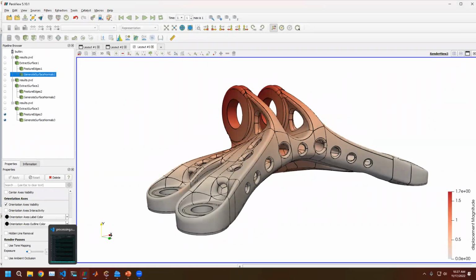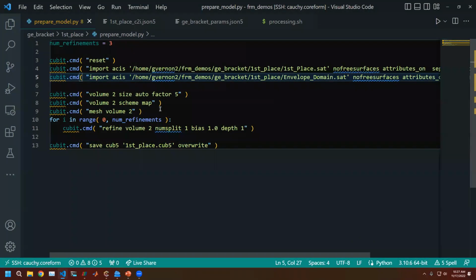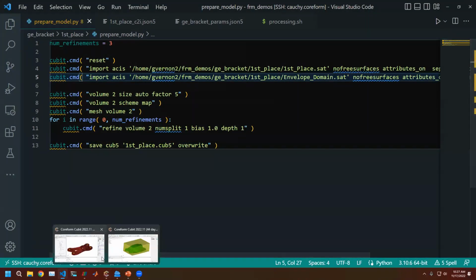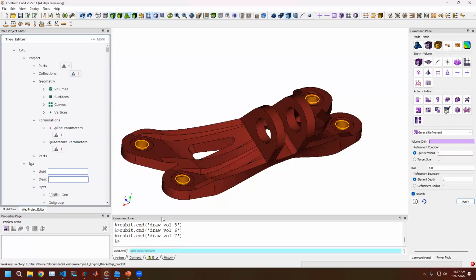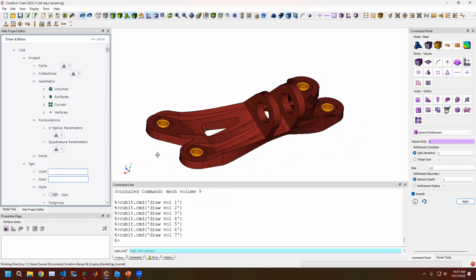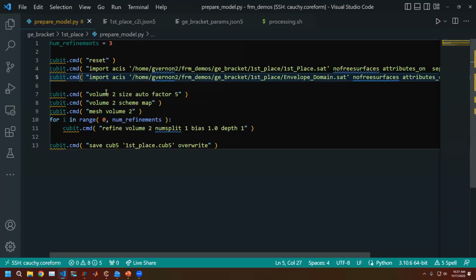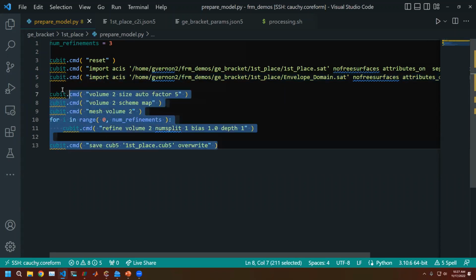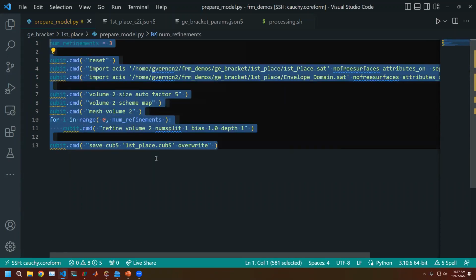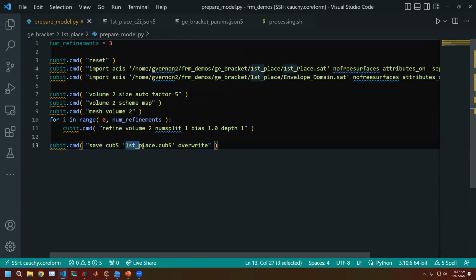And then because that process is the same for all of them, one of the things that we're also able to do is automate this. And so if we wanted to do all 630, I've just got a simple little Python script. Cubit allows for Python scripting. Every command that you do in Cubit can be accessed through a Python API for Cubit, and those get generated as you're operating in Cubit. So that helps you build up these scripts really quickly. And so this is a case where I can really rapidly prepare that model. Obviously, I could functionalize this, so I could do all of the different entries individually if I wanted. I could do even higher levels of scripting.